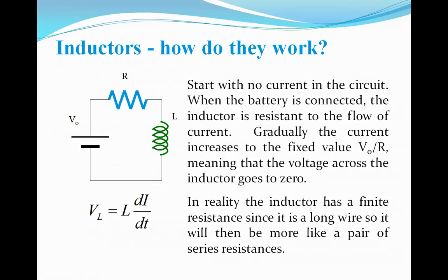And we said that phi is nothing but Li, because the magnetic flux is proportional to I. It means magnetic flux is equal to Li. So d phi by dt can be written as L di by dt. That is how we come to it: the potential difference across this particular inductance is equal to L di by dt. And because it opposes the applied voltage, it can be written as minus L di by dt.